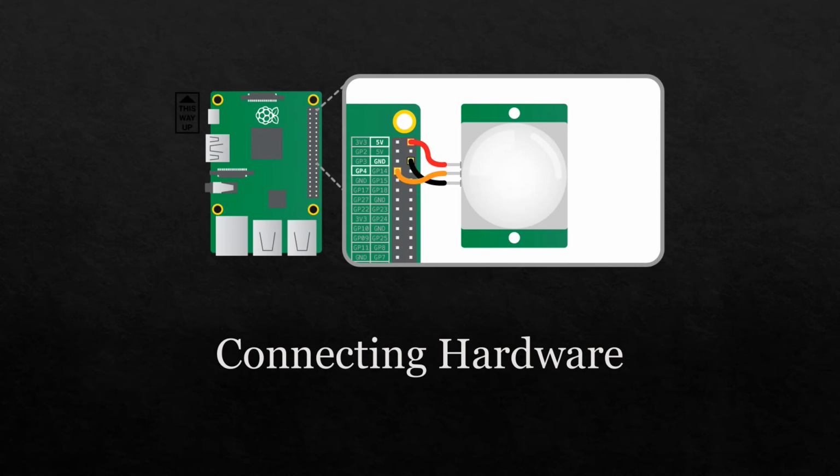The next step was to program the two hardware components to talk to one another in order for the motion detector to report on motions. Again, a tutorial was sourced which included Python code, which was then modified and simplified. I tested by moving in front of the motion detector, however I received no message in return. Upon looking closely at the hardware, I realized that one of the 3 wires from the motion detector had a loose connection. I took the device to an electronics store for advice, and it was confirmed that new wires were required.